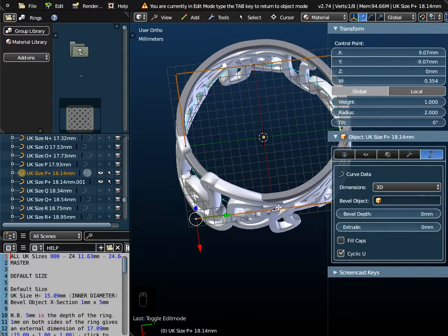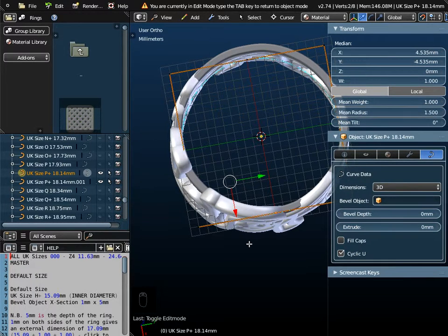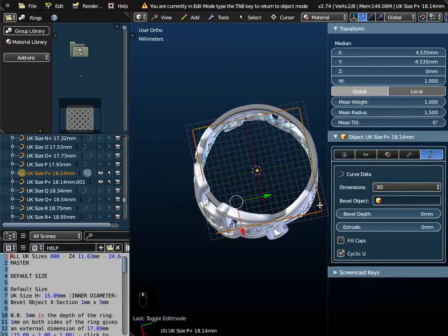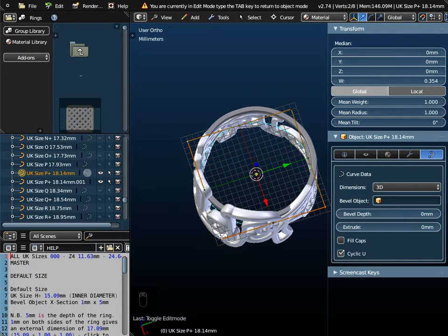Now what I'm then going to do is select the control point there, hold down the Shift key and select that control point. So I've selected these two control points. They're the first two away from this corner, and I'm going to type in a value of 1.5 this time. In other words, not quite as much. And then I'm going to select the control point in that corner, hold down the Shift key and select the other corner. So I started in this corner with the first point, then I did these two points. Now I'm going to do these two, and I'm going to do those at 1.25.